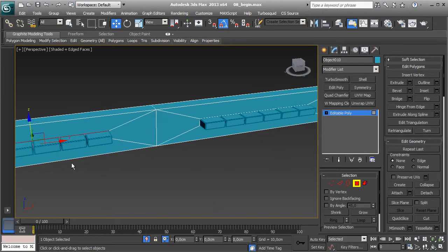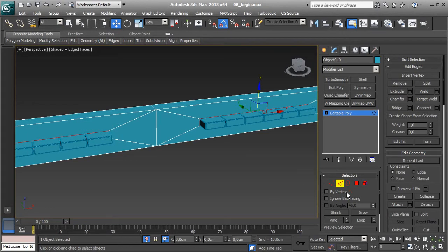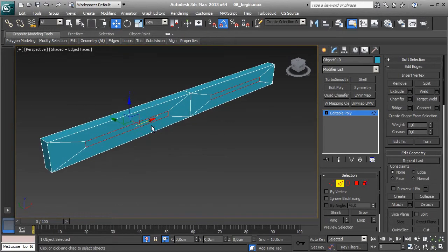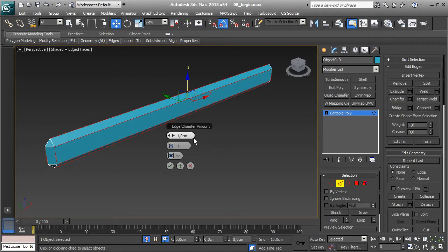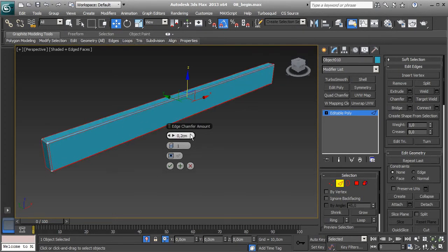let's select this polygon and this one and hit Control on edge, and now we have these inner edges selected, and hit grow and Control Backspace, and we can delete this one also. Now select them all, chamfer, actually let's do 0.1 centimeter and 3 segments.